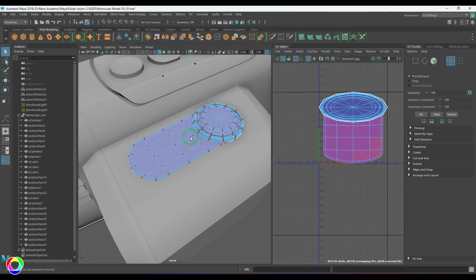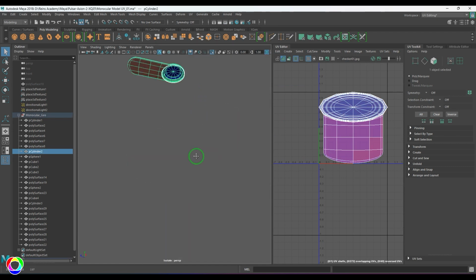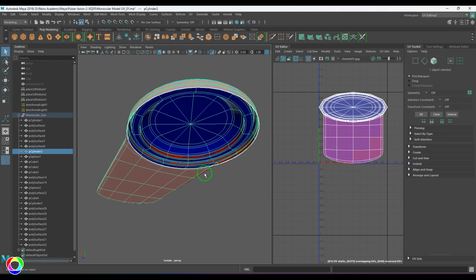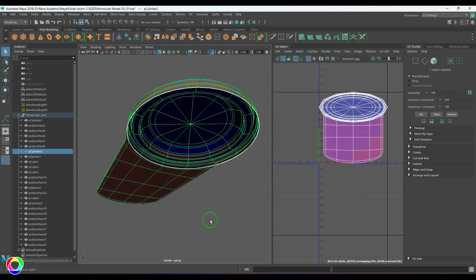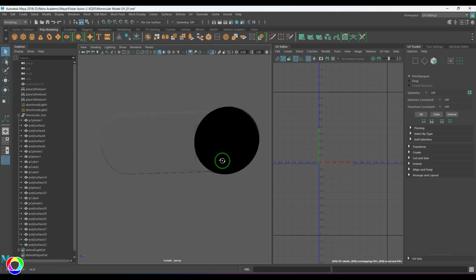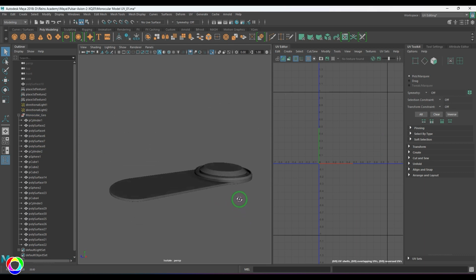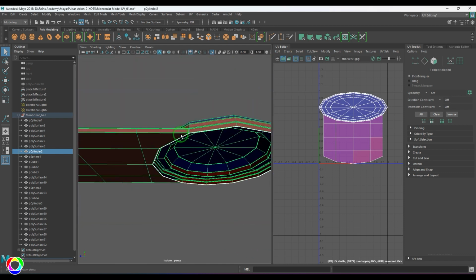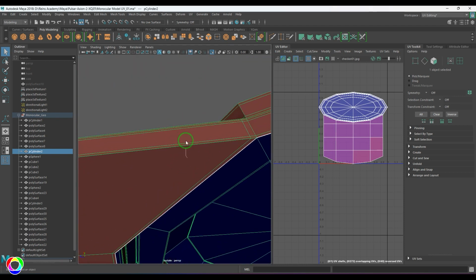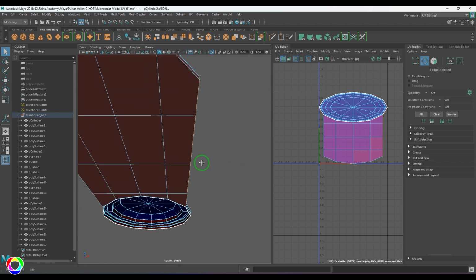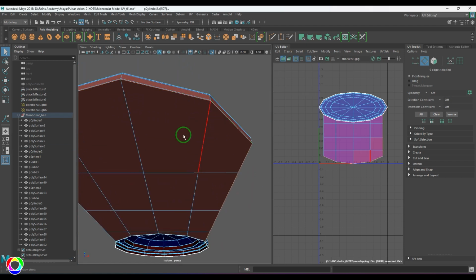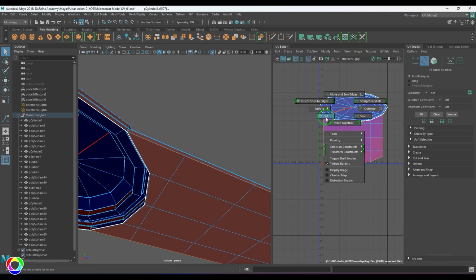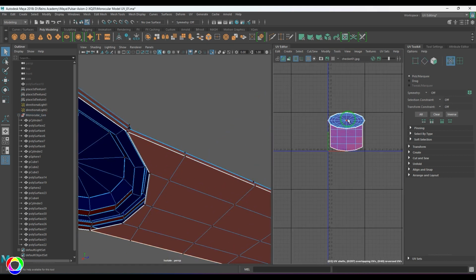Then you get this model. Just have a look at the model whether this model has got some thickness or not. Okay, if there is no thickness, then the model would get different UVs. So let me select this line. Okay, I'm going to use the cut UV and then separate them.